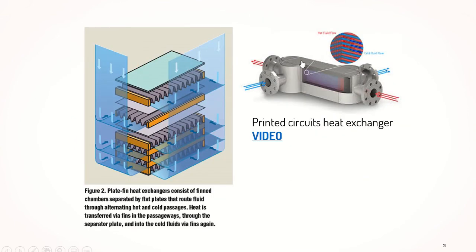And this would be a printed circuit heat exchanger. A printed circuit heat exchanger is very expensive, and it's very compact. I'm going to show the video later on, but not in this class. One single piece of equipment costs nearly 2 million ringgit, which is very expensive for a heat exchanger. However, because it's very compact and space saving, we use printed circuit heat exchangers on offshore platforms.